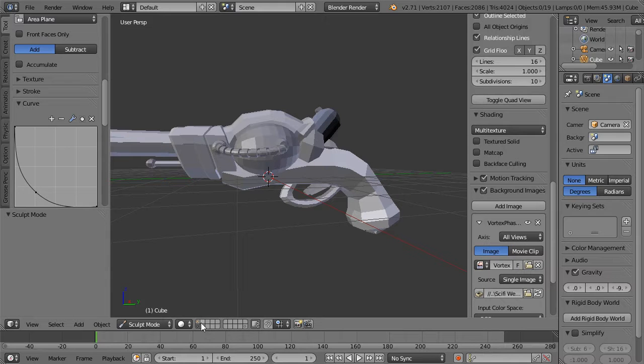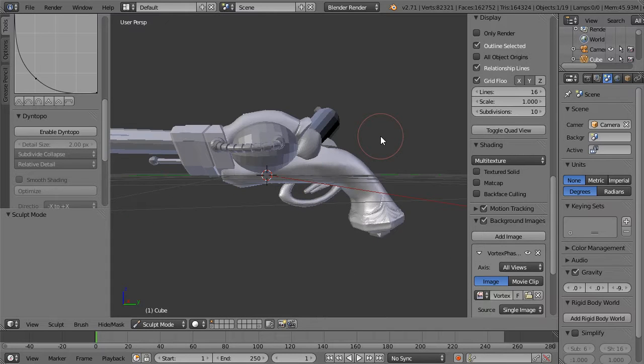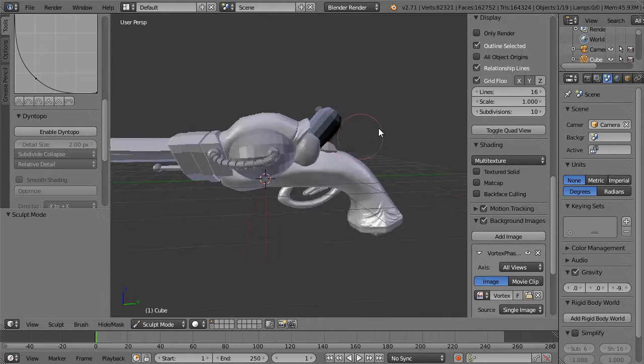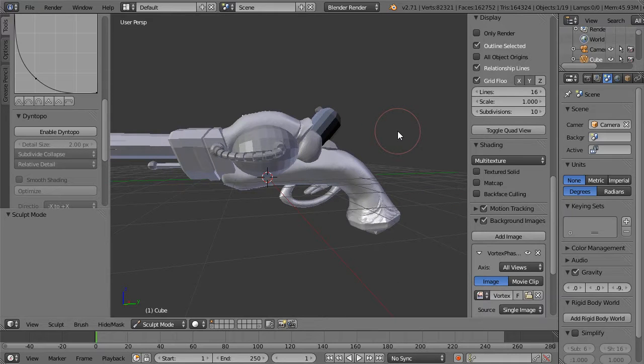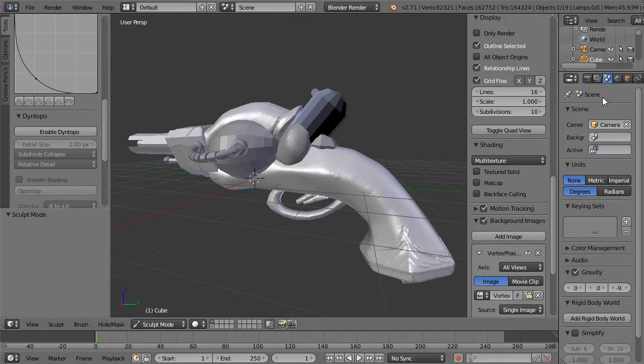What's going to happen then is that we're going to create our UV maps and then bring that information down to it, and then we're going to also use the painting tools on this mesh instead of this insane high polygon mesh. And that is to actually allow us to work on this model in close to real time, also without the caveats of dynamic topo. So what I want to teach you now is the aspect of masking.